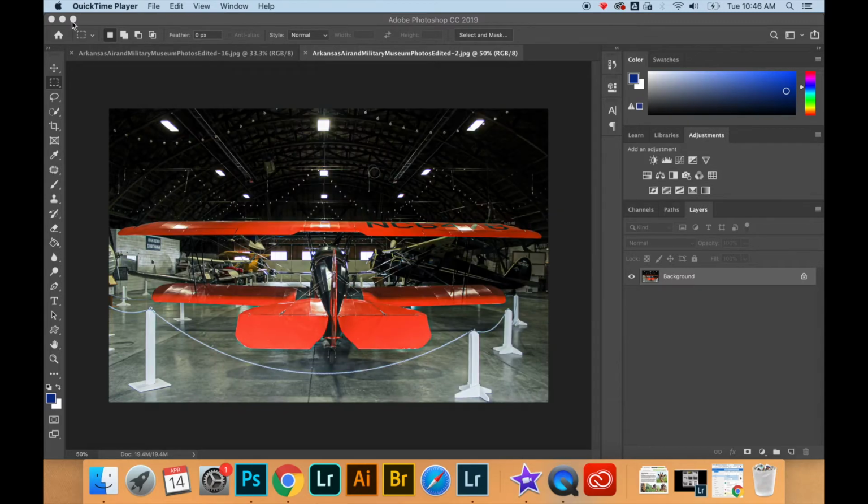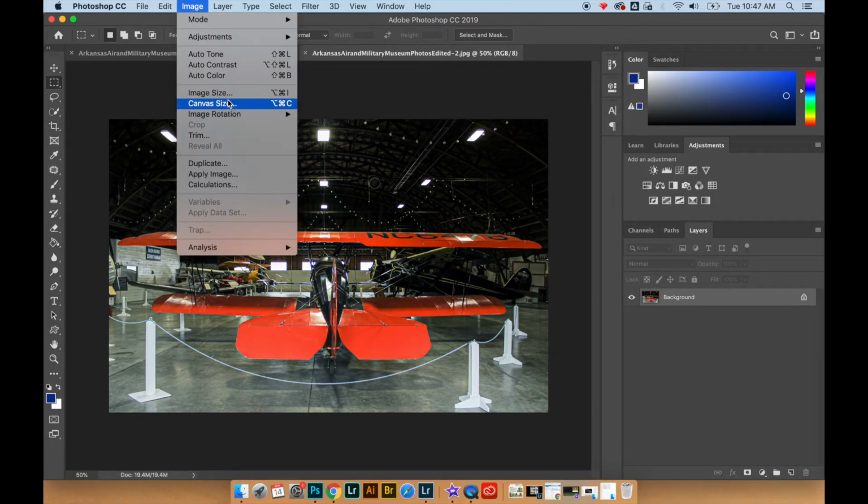So what I want to show you is how we can tell this information in Photoshop and how we can also reduce the file size by making it smaller. Oftentimes, while we're working, we have multiple programs open. All of this takes processing power from our computer. And so, if you feel like your computer is running slow, this will allow us to reduce the file size to allow you to work faster. So this picture that I have here, the document is at 19 megabytes, which is a huge file.